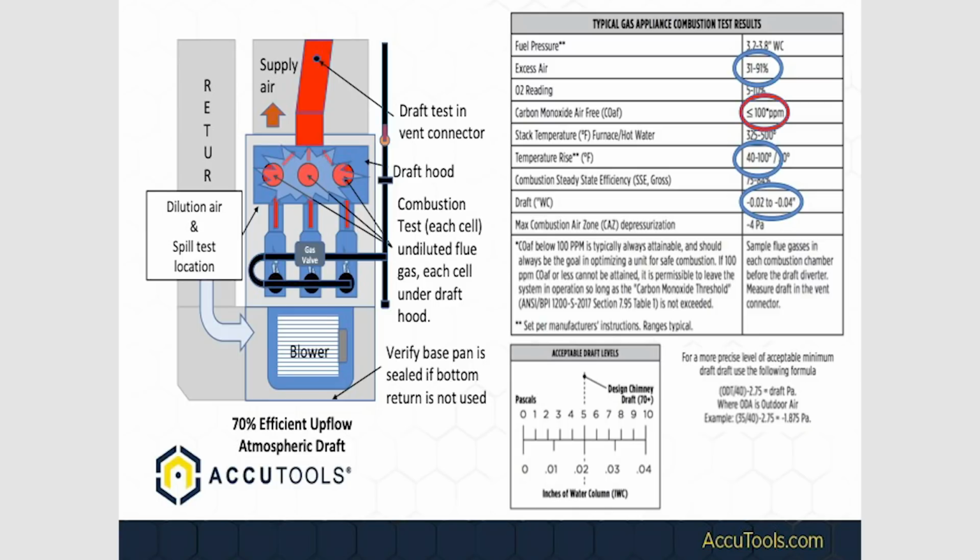So consider when you're looking at an appliance and you look at that combustion efficiency, that only tells part of the story, right? How do we think about the evolution of furnaces as we go? When we went to an 80% efficient, we eliminated the draft hood first. Did you guys remember we had 80 pluses with standing pilots? Any of you guys remember those? Then we eliminated the standing pilot. Then we saved more gas by putting in a secondary heat exchanger.